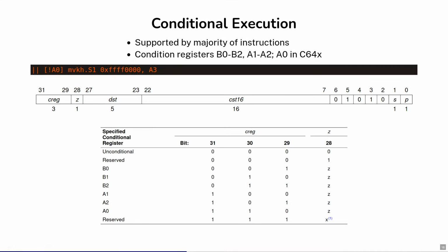One other cool feature that we can deal with is conditional execution. Nearly every instruction can be conditional. So it's not only conditional branches, but we could also say, for example, this is an instruction that sets the high half of one register. We had 32-bit registers and 32-bit instructions, so we need 2 instructions to fully set a register with immediate values. And this is one half of that, and it can be conditional.